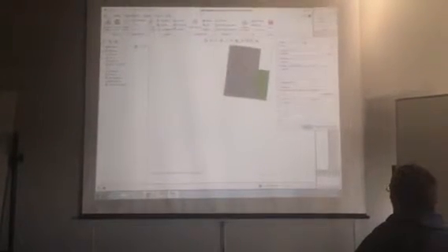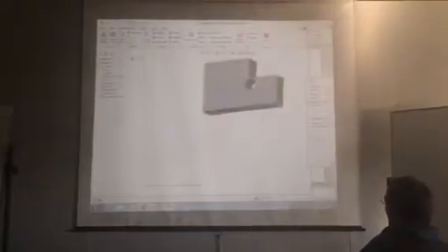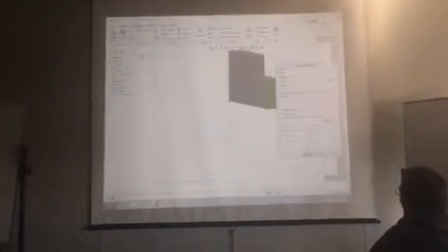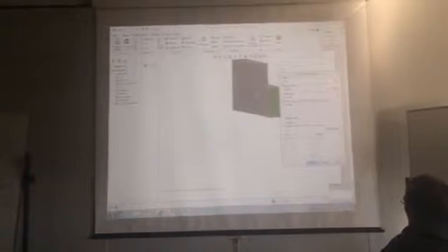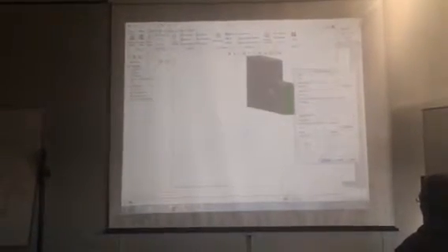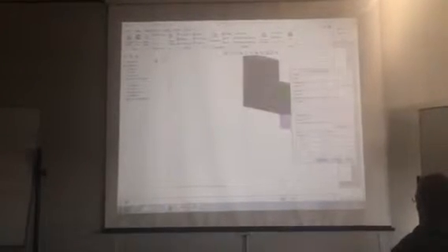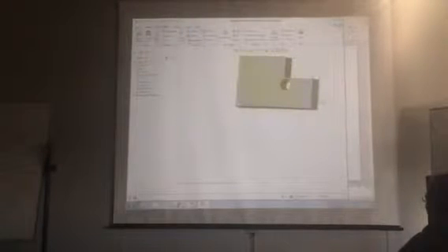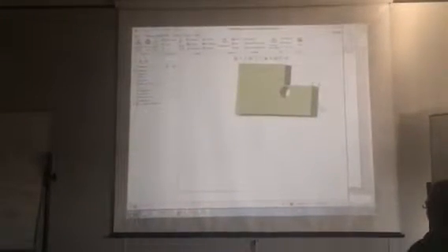So if I look at my directions, Y is the vertical direction. So in Y, I'm going to put a load here of, say, 2,000 newtons. Minus 2,000, so it goes down. Preview. That looks okay. So what I've got there is held at this side, going down this side. So this is what I'm saying for your parts.